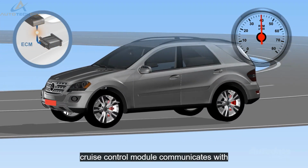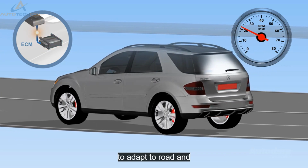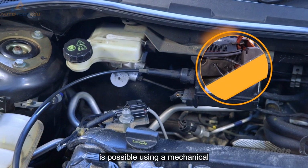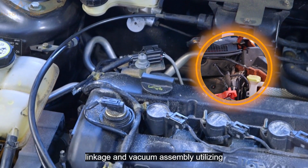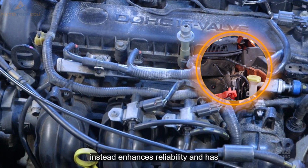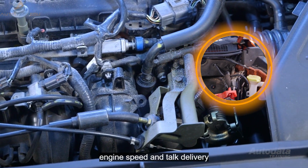The active cruise control module communicates with the ECM, adjusting the throttle valve angle to adapt to road and traffic conditions. Although this is possible using a mechanical linkage and vacuum assembly, utilising an electronic TAC system instead enhances reliability and has a much finer control over engine speed and torque delivery.